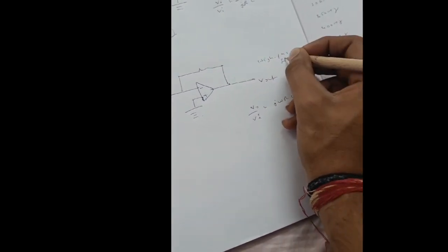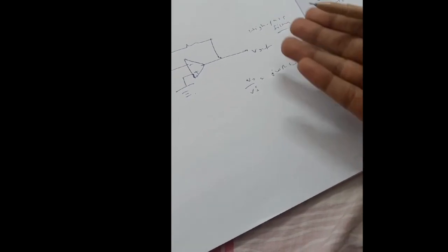Now here this will act as a high pass filter. Why? Because if you have high frequencies, the transfer function is high, so we'll get high output. If you have very low frequencies, we will not get a good output, which means that this circuit is allowing high frequency signals more efficiently.